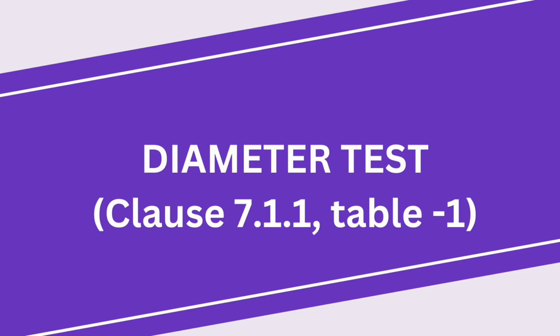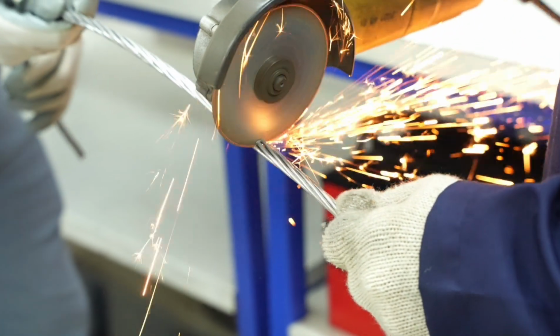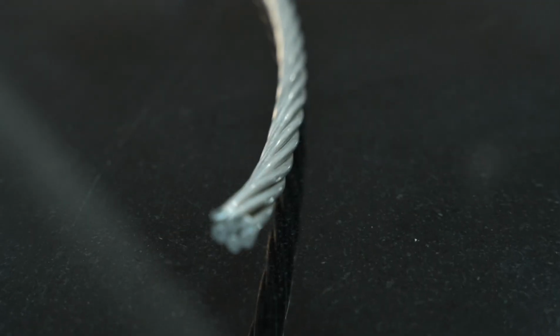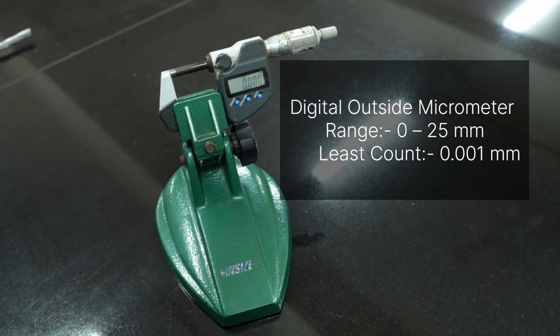The first test being demonstrated is diameter test. The diameter of a conductor directly impacts its cross-sectional area, which in turn influences its electrical conductivity. Maintaining proper diameter ensures efficient current carrying capacity through the conductor. The equipment used for this test is digital micrometer.